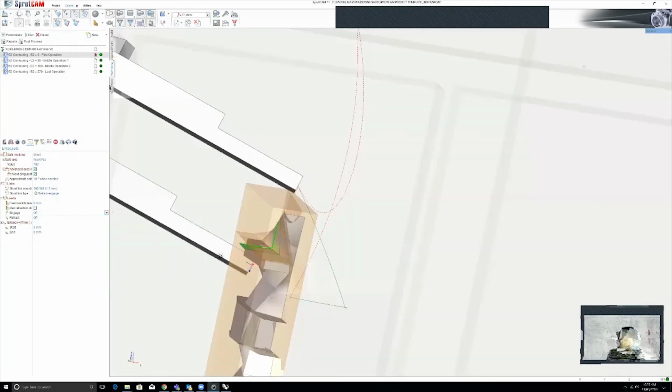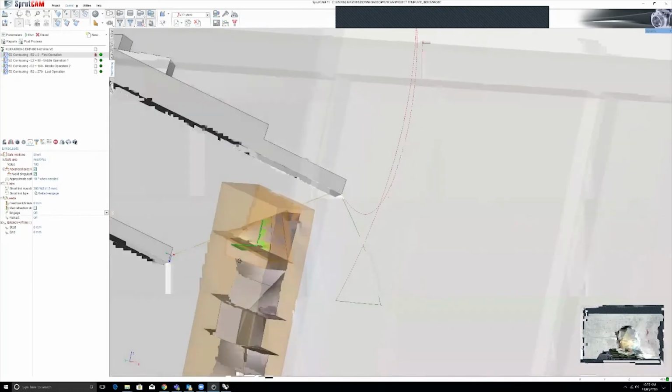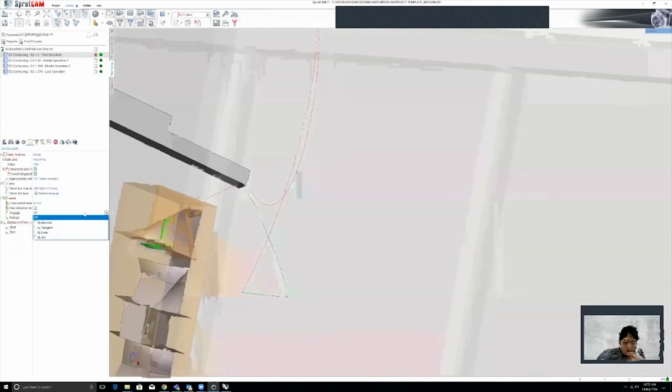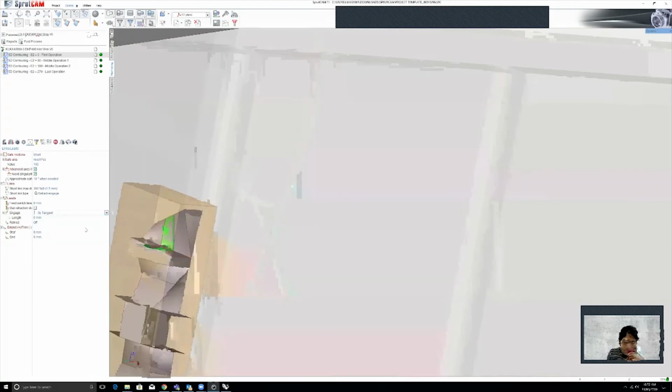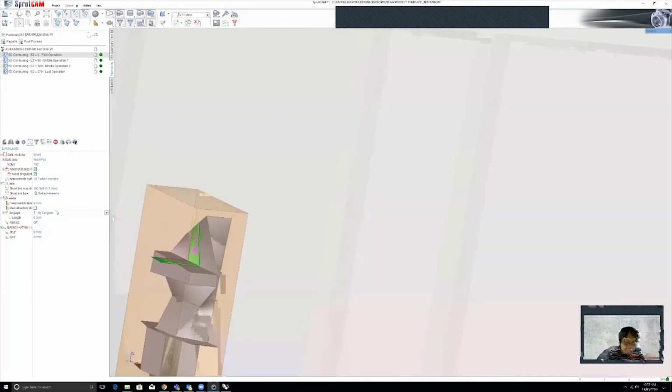So let's go ahead now, and let's just do it by tangent, so that when we are coming in and cutting the block, we can just come straight down. So I'm going to do it by tangent. And then here there's an option for you, the length. How long do you want that cutting surface to be? That's the engage length. And I'm just going to say by default, I'm going to give it 100 millimeters. Enter.